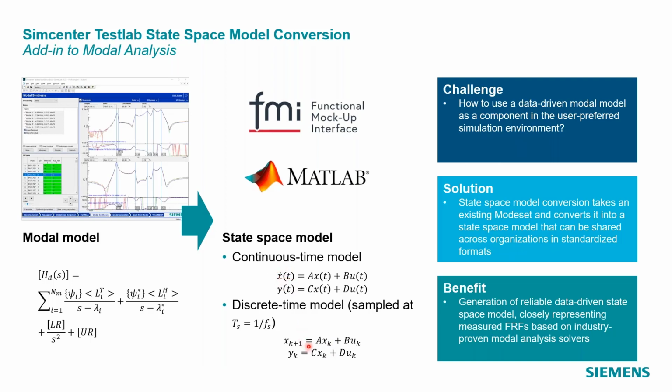The discrete time model is a bit simpler because these are just recursive formulas, and this is a bit more logical for measurements. There you also have a certain sampling frequency, so your data is sampled, so you have the samples of your input, and you can easily calculate your output of the model. It's just recursive formulas. Here you would need some time integration methods, so that's a bit more complex to solve. Discrete time models are a bit easier.